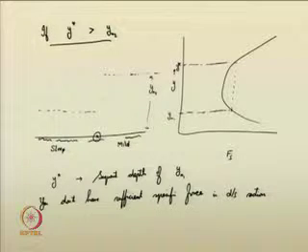So, how will the hydraulic jump be formed then? The hydraulic jump will be formed in such a way that it will realign the flow. First, the hydraulic jump is now pushed into the downstream section. Here it will be pushed like this, and that pushing is described through a gradually varied flow profile. It will be an M3 profile, as you know. The water races like this through an M3 profile, and you have to check the corresponding depth here.